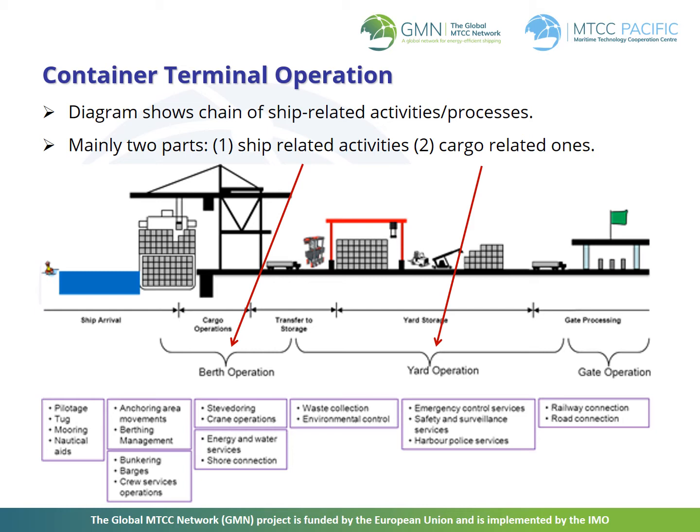In dedicated container terminals, container boxes are unloaded and loaded, usually using a gantry crane at the apron, where containers are moved to and from storage by in-terminal movement vehicles. Once the container cargoes are unloaded, they are transferred to an assigned slot. This is the space in the yard where storage operations occur. The containers are stored until they are inspected and claimed by the consignee or importers.